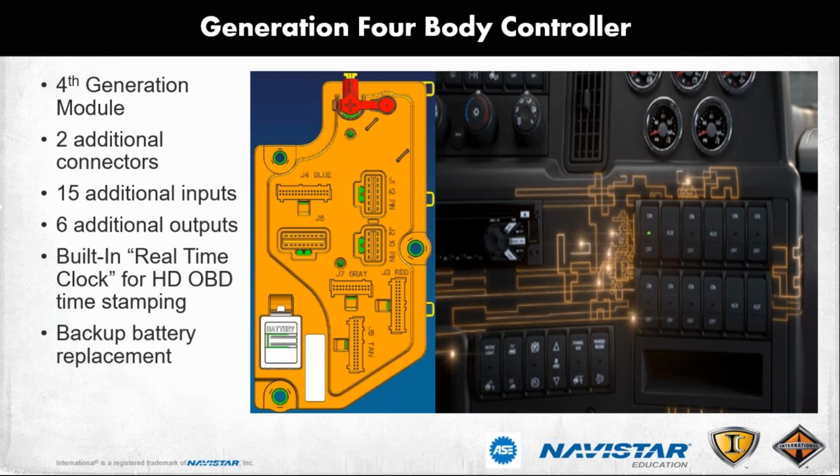Initially, there's nothing on the back side of it. When the battery that's soldered in fails, you can buy a replacement battery that goes on the back side of the cover. It's plug and play. A little pigtail plugs into the circuit board. And what we do from there is we'll go into our software, and our Diagnostic Builder software is a good example. It will allow you to resync the time clock. So what it's going to do is take the date and time off the laptop. It's going to compare it to the body controller. If they're not the same, it will set a fault. Then in the software, it's kind of automated. It'll pop up a screen that says, do you want to synchronize this? And just say yes, and it's done. That's simple.